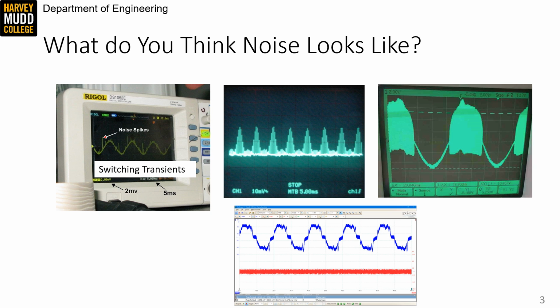The large spikes in this trace are caused by a switching power supply. The power supply doesn't seem correlated with the sine wave on the screen, but its behavior isn't random. It's actually periodic, and you might be able to pick out the switching frequency from this trace.